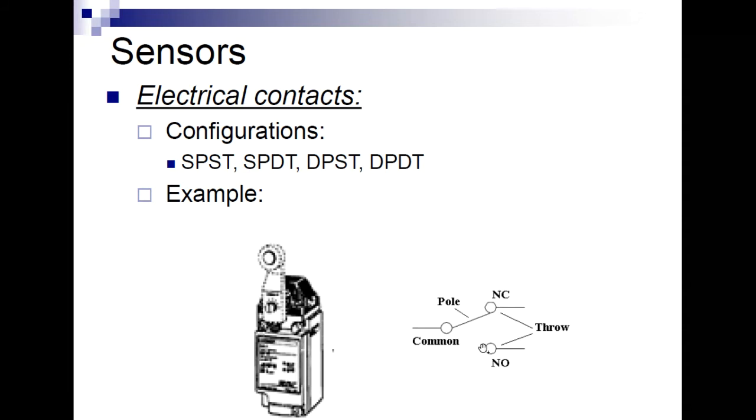All right, now in this picture right here, I have one pole. It's possible you could have multiple poles. So this configuration up here is talking about the number of poles, P, and the number of throws. In this case, this switch shown down here, I have one pole, so single pole, SP, but 2 throws, double throw.